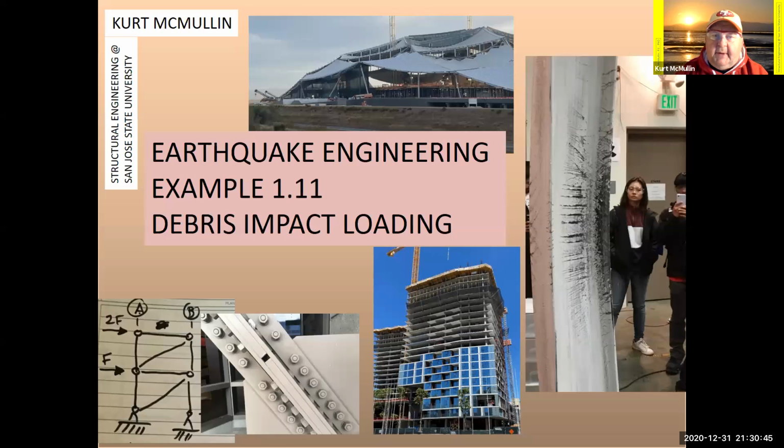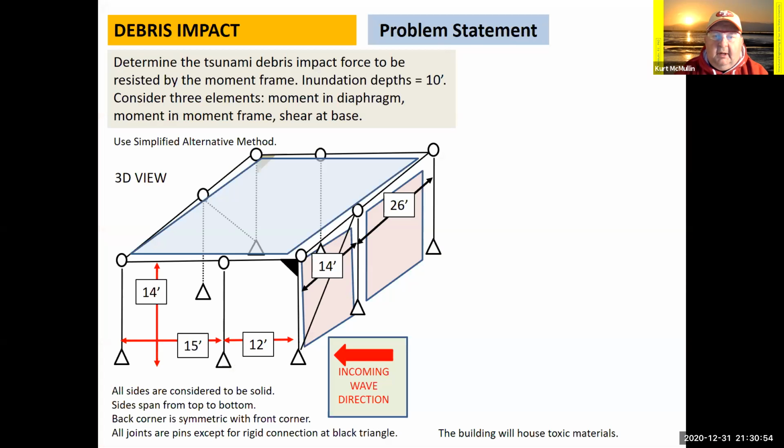So we're talking about what kind of force I need to resist or design for to consider just this debris impact loading. I'm actually going to use the same structure as what I did in my previous example. Now I'm only going to talk about an inundation depth of 10 feet.